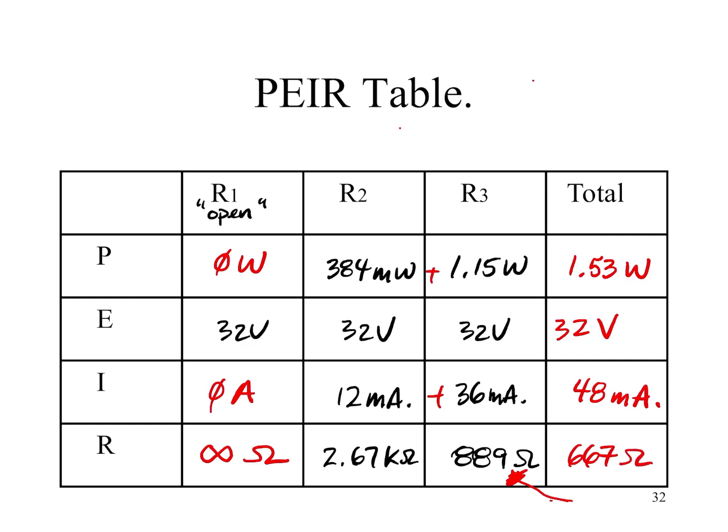And notice how that's considerably more than what we had previously, where we had 400 ohms. So notice how we took a fault as an open within the parallel circuit and looked at its new values, and based on missing branch 1's current, we had less total current, less total power dissipated, and more resistance, or more R total.